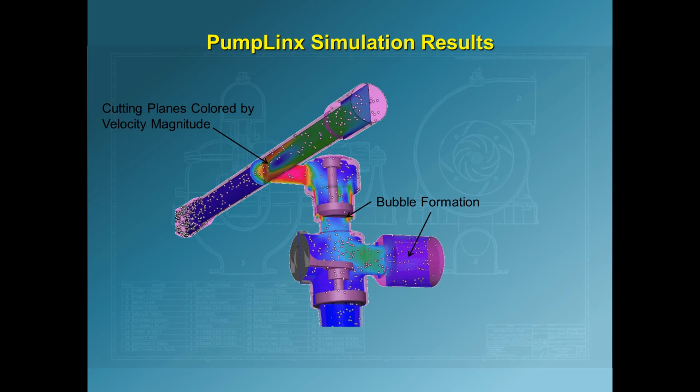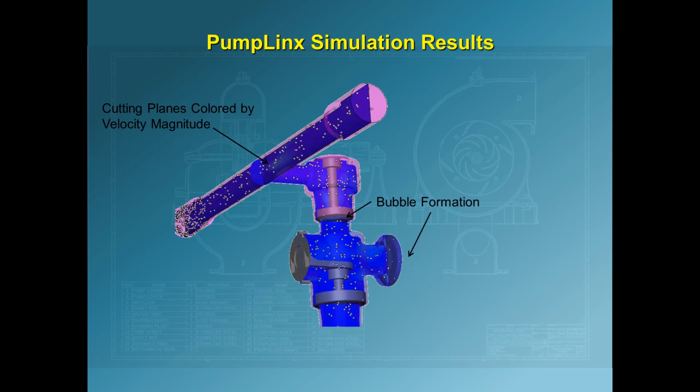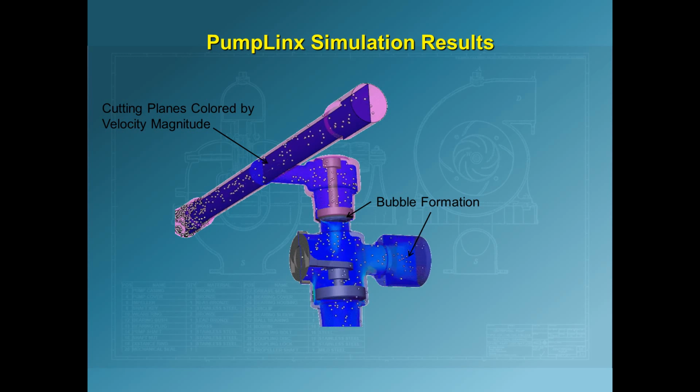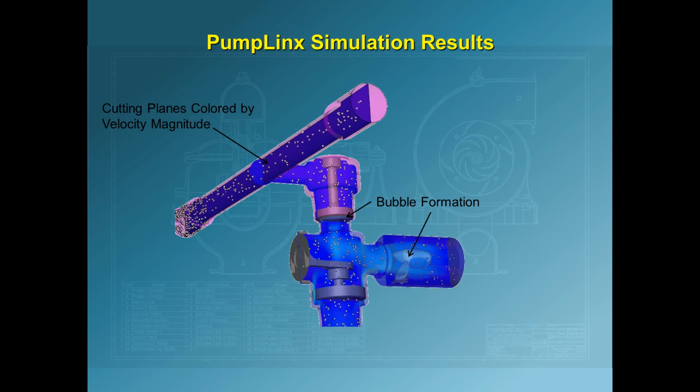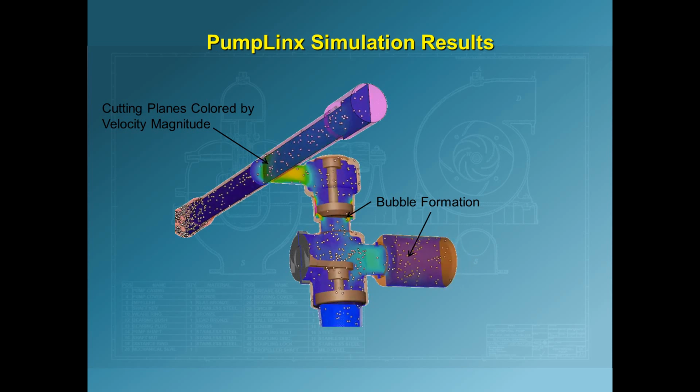In this simulation, PumpLinx predicts the motion of the valves using the force balance of the pressure integrated over the valve surfaces, the valve mass, and the restoring spring force. PumpLinx can also model valves which are controlled by a solenoid.